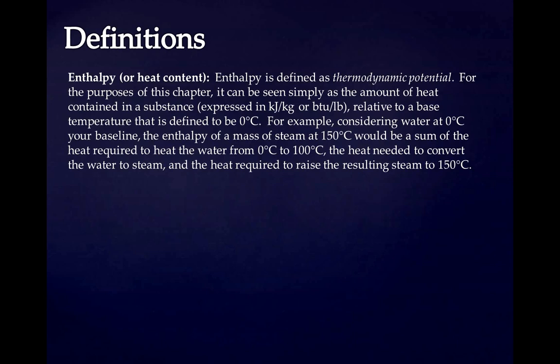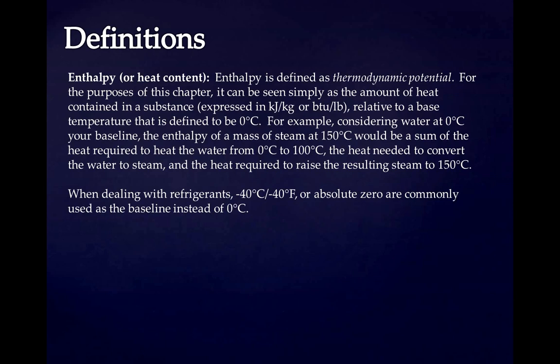For example, considering water at 0 degrees Celsius as your baseline, the enthalpy of a mass of steam at 150 degrees Celsius would be the sum of the heat required to heat the water from 0 degrees Celsius to 100 degrees Celsius, the heat needed to convert the water to steam, and the heat required to raise the resulting steam to 150 degrees Celsius. When dealing with refrigerants, negative 40 degrees Celsius, or negative 40 degrees Fahrenheit, which is the same thing, or absolute zero are commonly used as the baseline instead of 0 degrees Celsius.